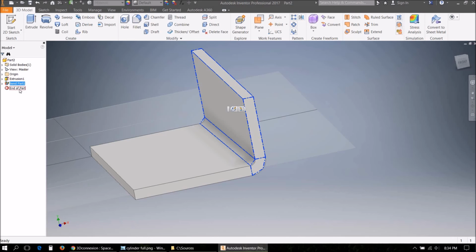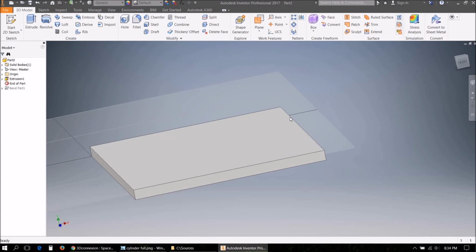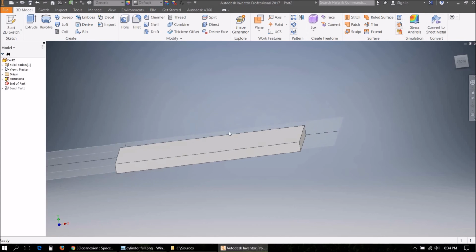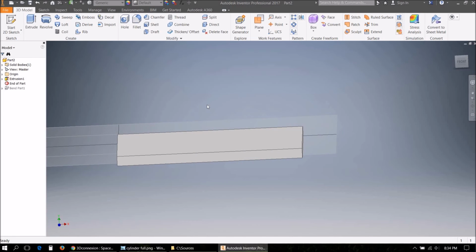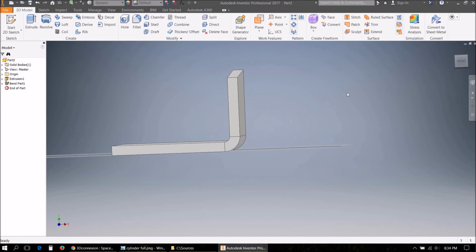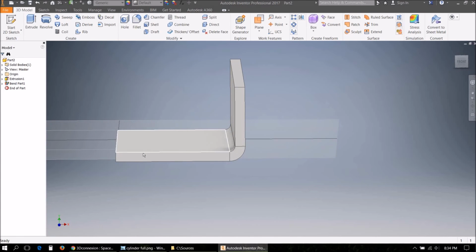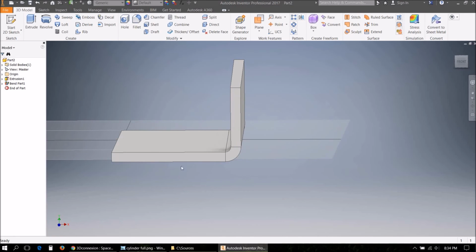If you delete the bend part, I can just simulate it by moving the end of part file up, then the model will return to its original position. Now you don't want that. So instead of bending a part using the bend feature, model it just so that it's basically at the right angle, and then use fillets instead to simulate the bend. Here, let me show you what I mean.